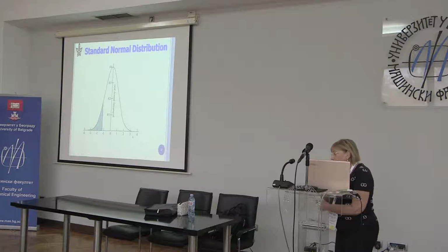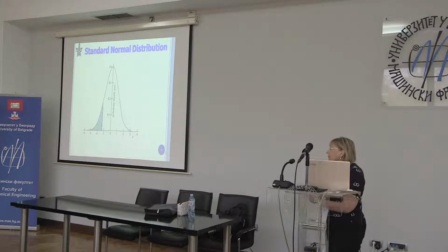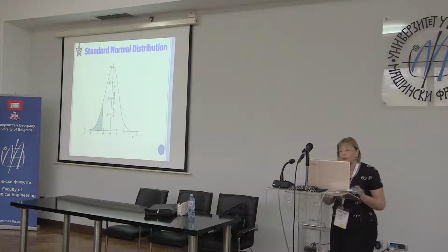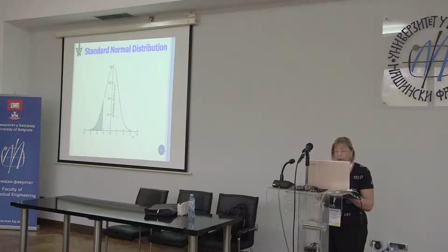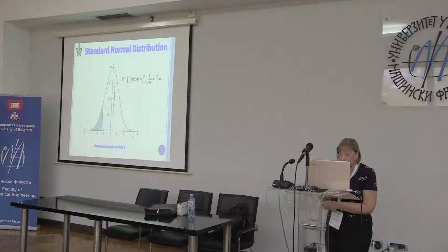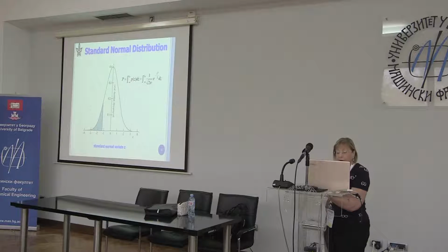And as I said before, we saw that there was scatter in the data. So we looked to do something statistical, and we made the assumption that the G1C values have a normal distribution. And so the probability of unexpected failure in this zone is governed by the integral of the probability density function from 0 to ZP.